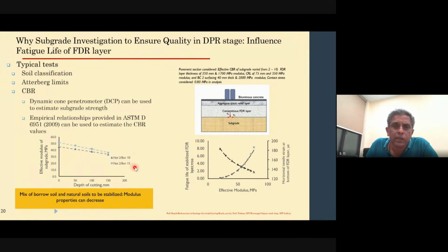Then in terms of mix design, ideally speaking, about 175 to 200 kilograms might be an approximate number that can fit all the test methods and processes that are involved in mix designs. This is about the quantity that needs to be sampled. Now, critical parameters for success: meeting gradation of mix design and field. Now, capturing the variability in the field by making proper sampling. These two can actually go a long way in defining the success of any given FDR project.